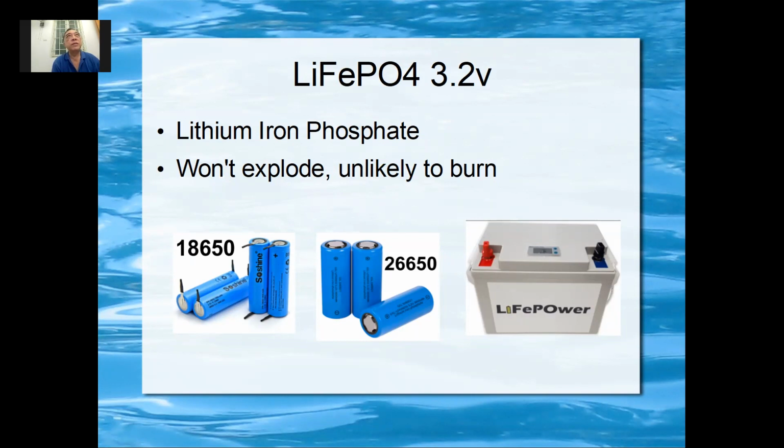The only problem with this lithium iron phosphate and lithium ion battery in, let's say, a battery pack is the voltage difference. Let's say you want a 12 volt battery. Normally they use 4 pieces. If they use 4 pieces of lithium iron phosphate battery, you take 3.2 times 4, which gets you 12.8 volt.